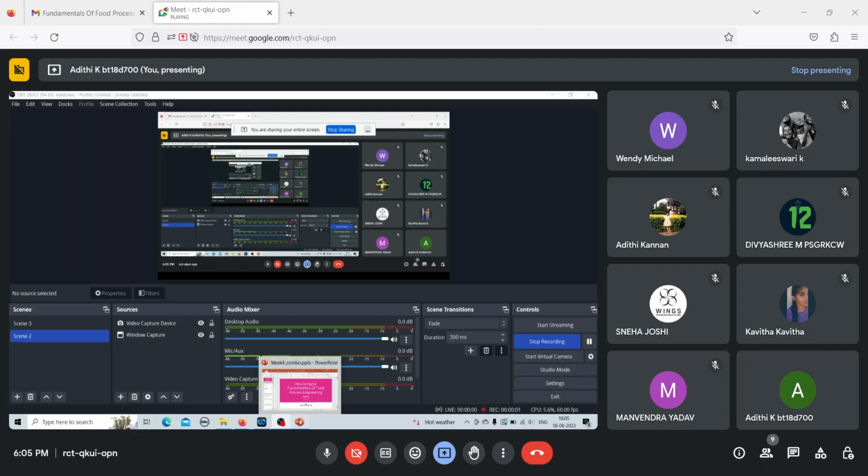So this percentage is basically the total solids that are present in the stream. So 8% is what is present in the feed, so that is equal to XF. So XF can be given as 0.08, and it is concentrated to 26%, which means when you take out the product, your total amount of solids is now 26%, which means XP is equal to 0.26.